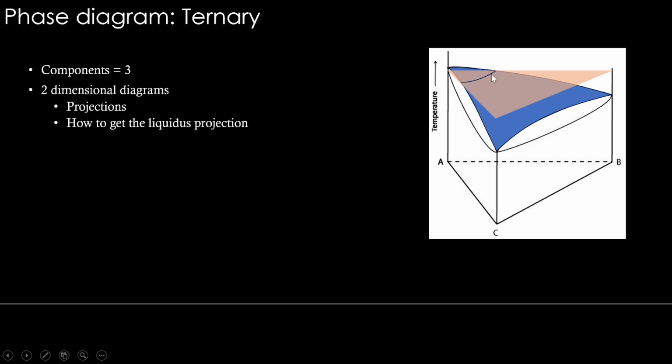So this entire line has one single temperature. Okay, so this is a contour of one single temperature in the liquidus surface. And we know the compositions on one side of this line would have started to form solid, while the compositions on the other side would not have started to form solid, they will be still liquid. So that is what this contour line means.